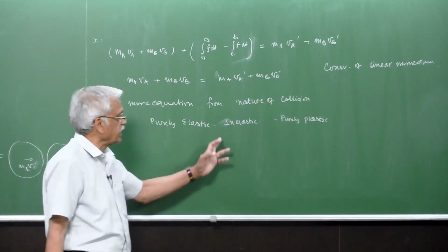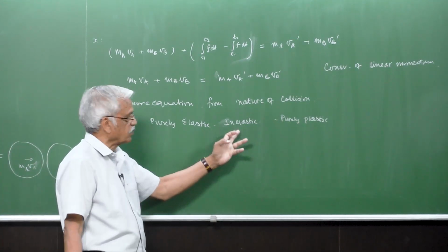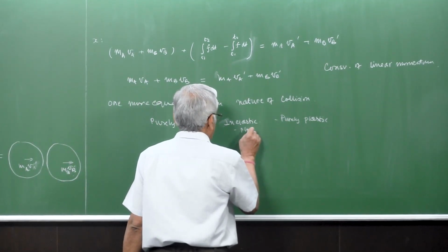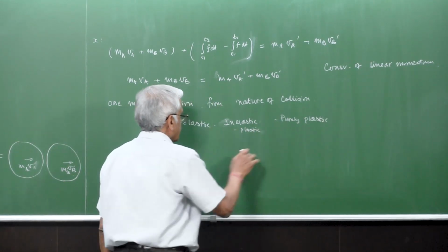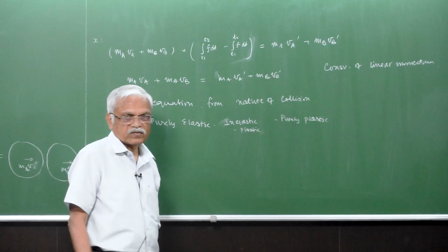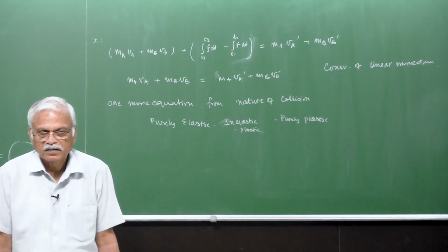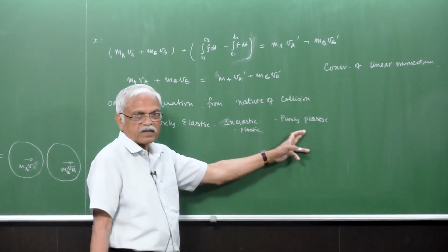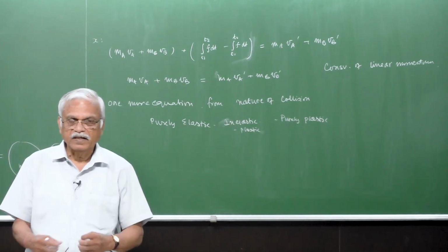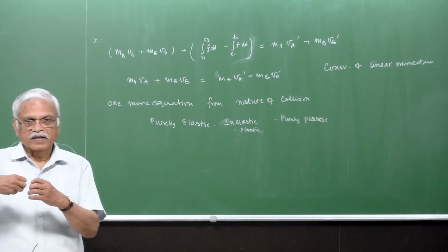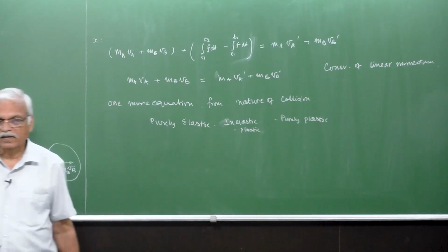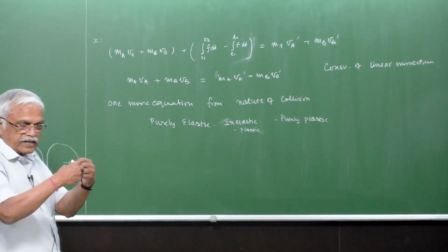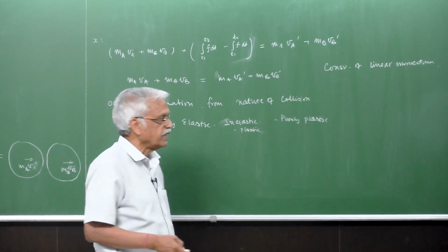Okay, so that's purely plastic, and somewhere in between it is also an elastic-plastic kind of collision. So if you go to these two extremes, what are the kinematics that are affected by the kind of material behavior? In the purely elastic case, whatever deformation takes place is completely recovered, and the energy that went in to deform it is completely recovered.